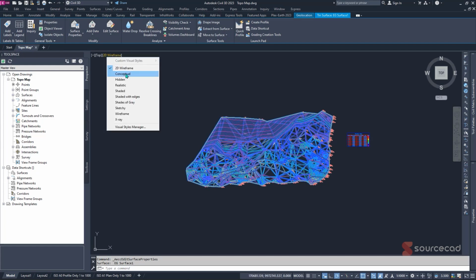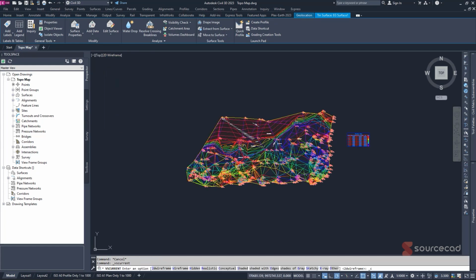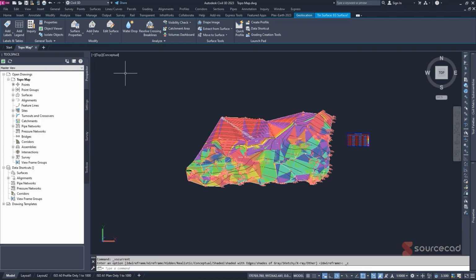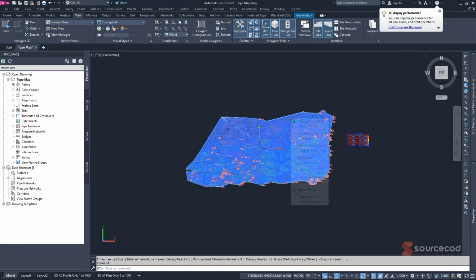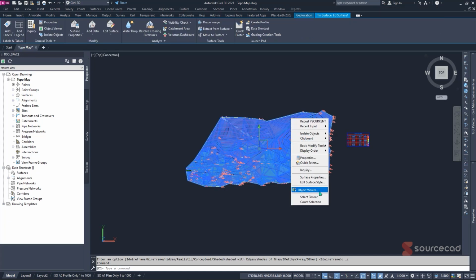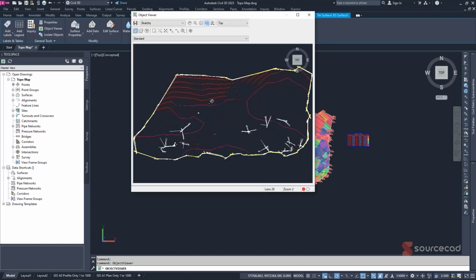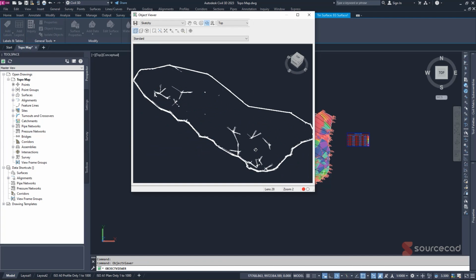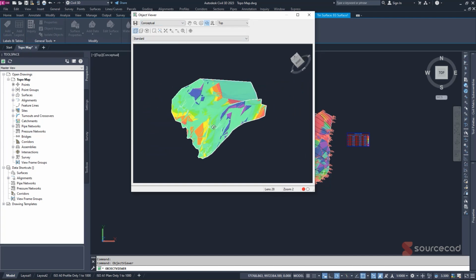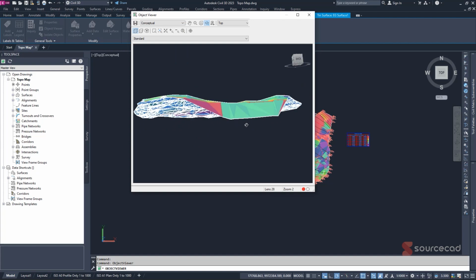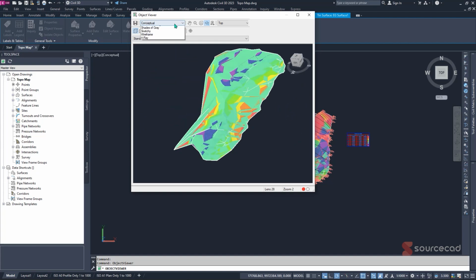And remember, you can always change to conceptual so that you just see it in a 3D way on how the areas and the curves are just moving all along around this area. But it usually uses up some of your space. But you can right click always and just simply go to object viewer. And under the object viewer, you can still find the same thing. You can be able to orbit like so, hit conceptual, and just see how your surface looks like. So this is how our surface looks like.